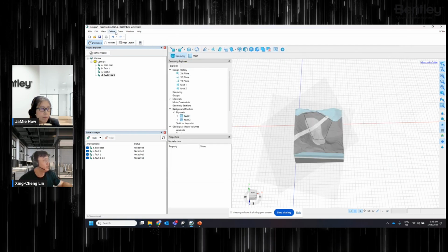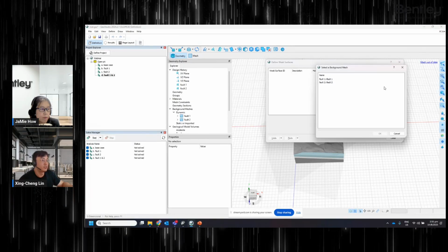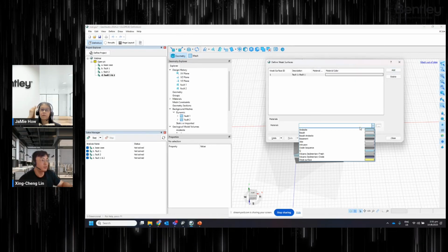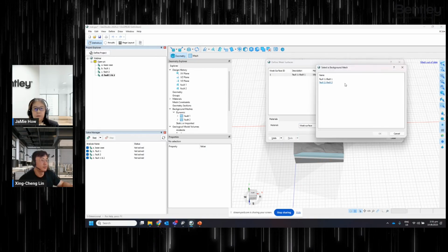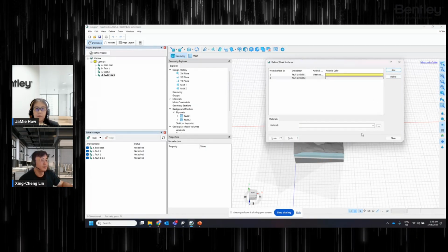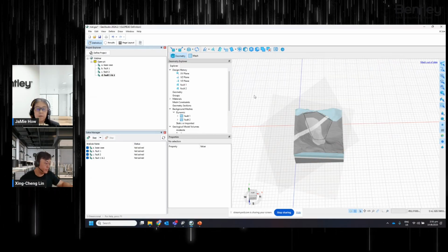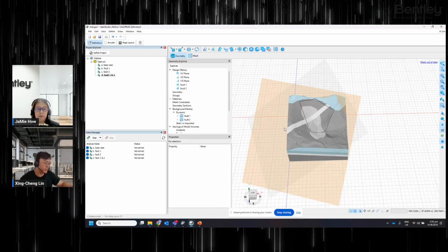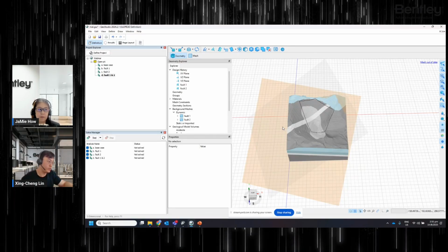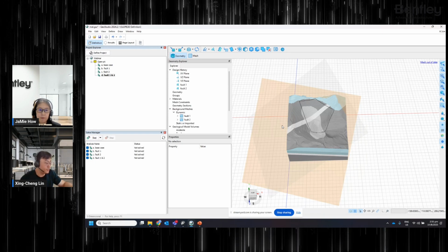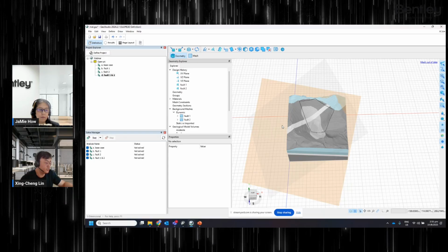In this case, we need to define which are the active weak surfaces, so we need to actually add two background meshes. So there you go. This is how we finish the setup of models and materials. Once we have imported from Leapfrog work, this is how to actually translate into analytical models that are ready for analysis in GeoStudio.